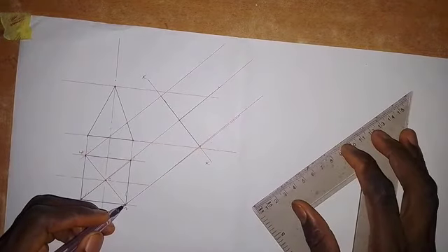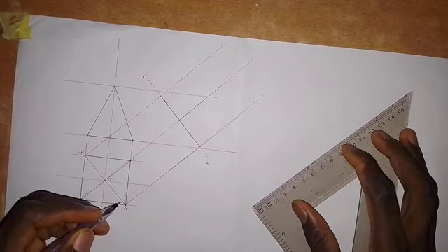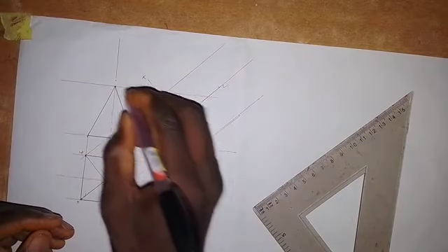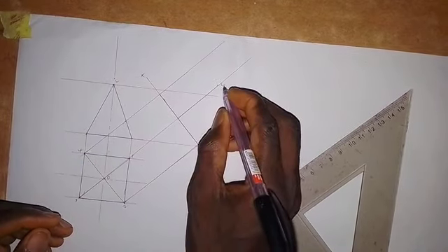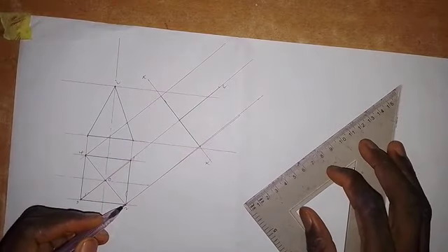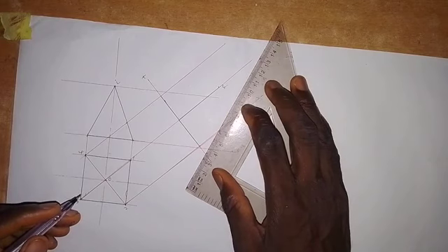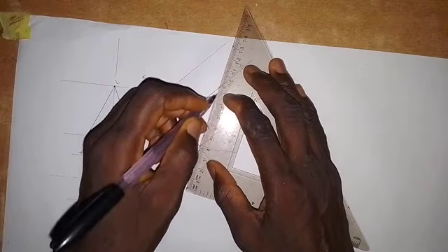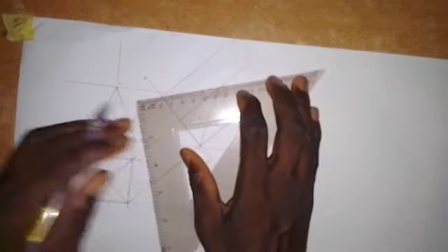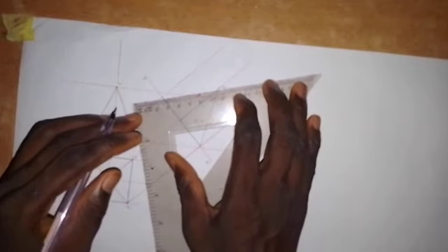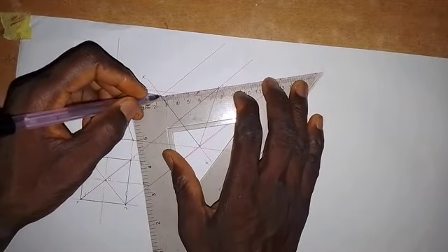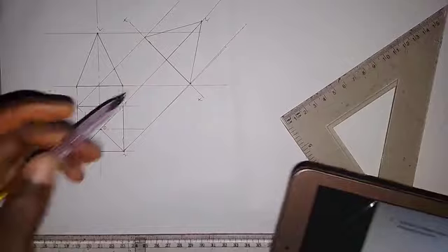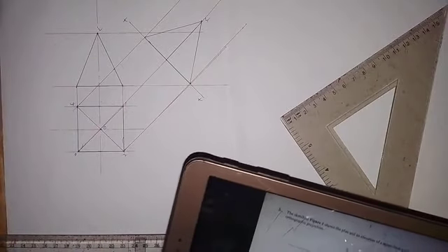Also, I will see a line at this point 2 here that is joined with the apex. So let me call this point V, as we have here. So this is V, and let me call this V1. We are going to see a line from point 2 being joined with the apex. So I'm going to make this line a thick line. I will draw from here to here as a thick line. Also, we see this line being joined together with the apex. So I will also draw this. Alright, here we have the auxiliary elevation, as you can see here. So that's the auxiliary elevation.